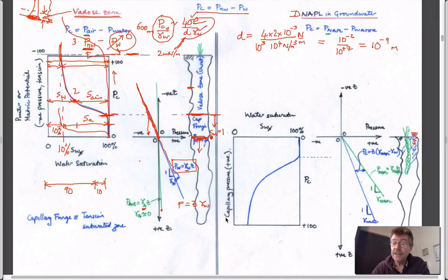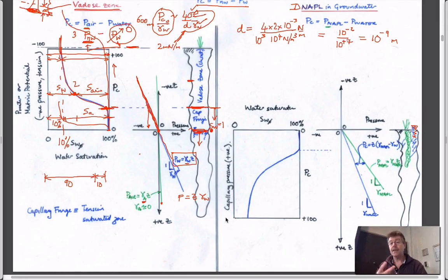So if you imagine this now for the case at hand, for the opposite case, instead of the case where we have the vadose zone, and we look at a DNAPL going into the system, the same behavior applies. Perhaps it's easier to visualize. You have a DNAPL, which in this case is our green component here, which has a ganglion that goes down. It's denser than water, and so if you look at the pressure change as you go down, so long as it's simply connected, it'll again increase in pressure more quickly than water. If you go down through the water on the outside, then it will increase in pressure more slowly.